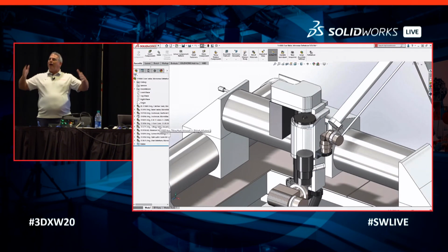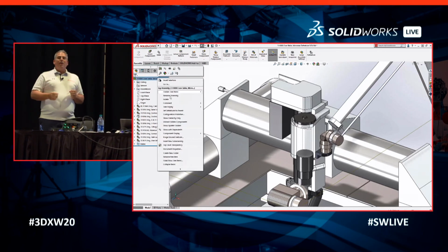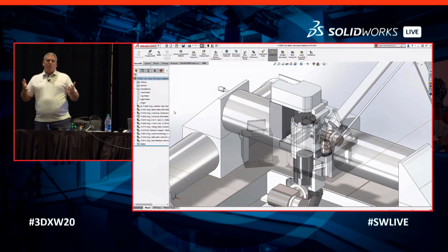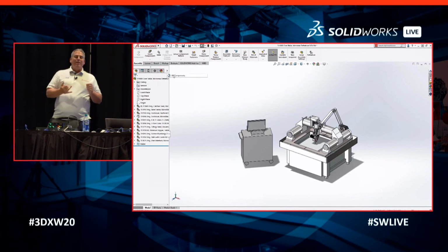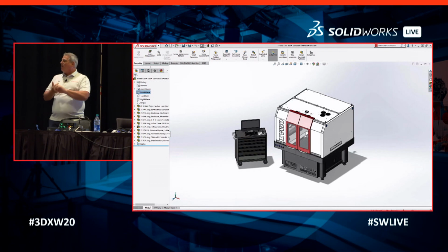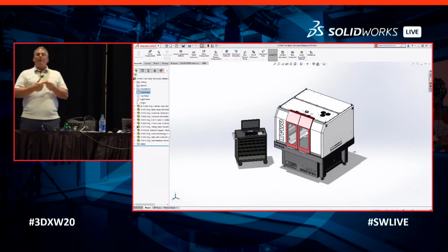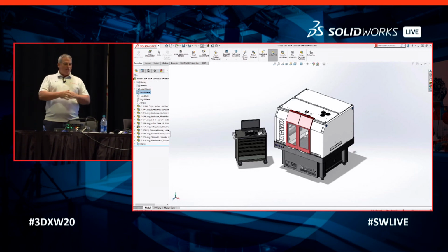You can imagine how this piles up as you get to the top of these massive assemblies that you're creating. You have the flexibility to swap from simplified to fully featured as you see fit for whatever purpose you need. And it's great. They're just a derived configuration. They work exactly as you would expect. They work with section views, with LDR. They work with interference detection. They even work with downstream applications. I actually used this for flow simulation to simplify the geometry when I played with this. It's an incredible game changer for us.